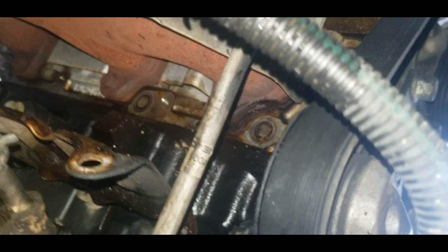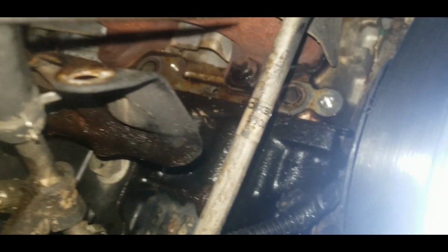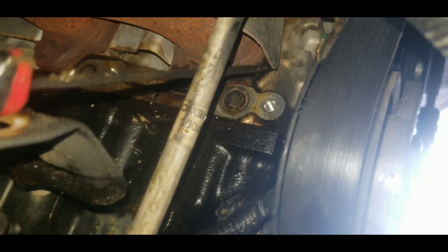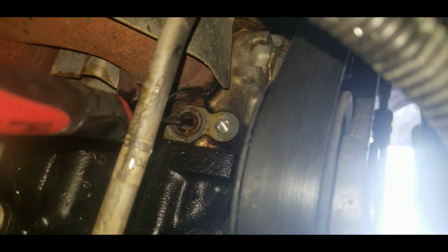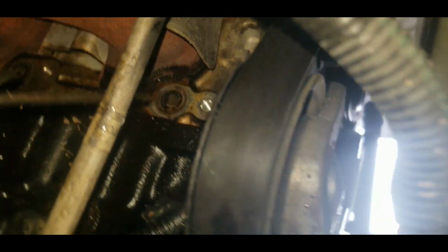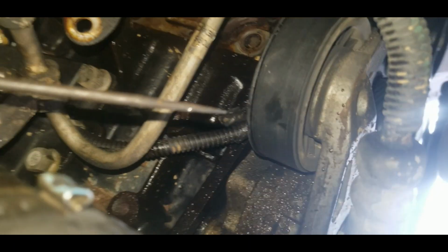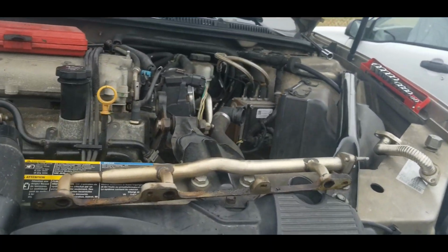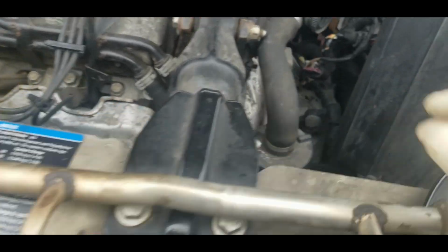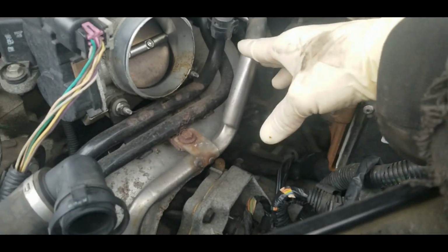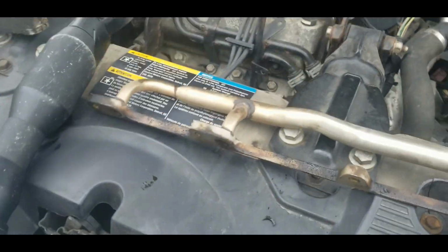So another thing you want to do is put a pick in the hole of the cylinder head itself, which I'm trying to get to right now. And yes, the pick goes in, no problem, and it comes out pretty clean. So the cylinder head is not clogged, and I would assume the exhaust manifold is not clogged up either. So our flow is fine, we don't have any cracks anywhere in these pipes. Our problem is not that the system is clogged up.